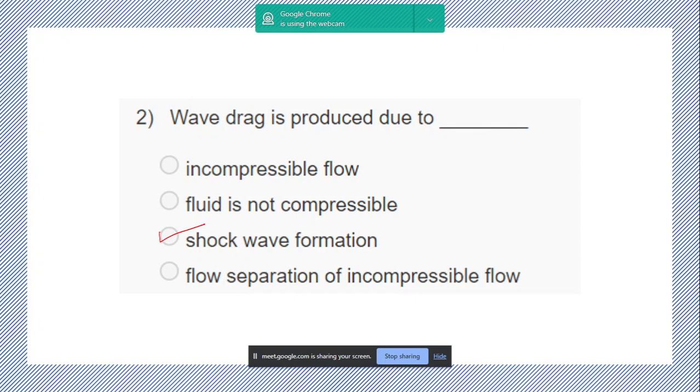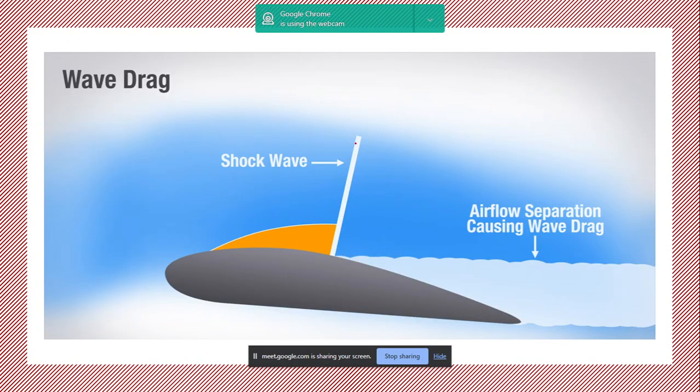Okay, I think you can say it a bit clearer. Let me just try to show you the image. There is a shock wave that's created here. After that, in the wake of the shock wave, there is turbulence, and the turbulence is not smooth. Like he said, it's not smooth. It causes skin friction drag. All the forces here are not smooth, so they have some additional skin friction drag terms, which is why you have additional drag components when the flow encounters a shock wave.